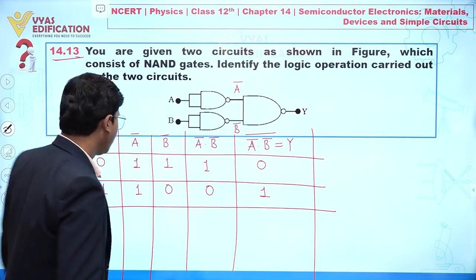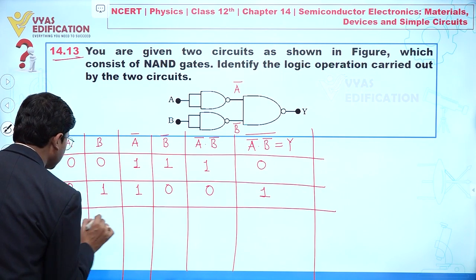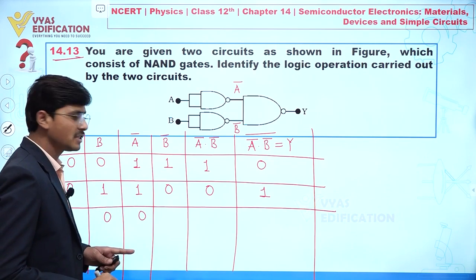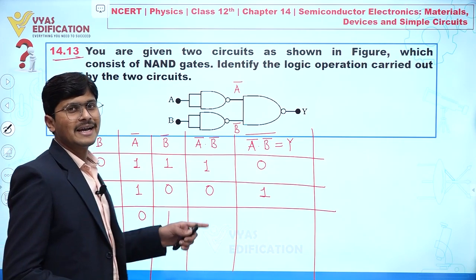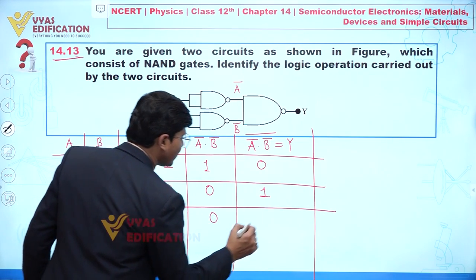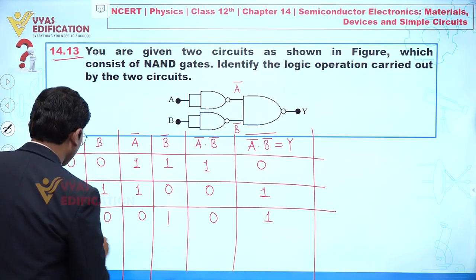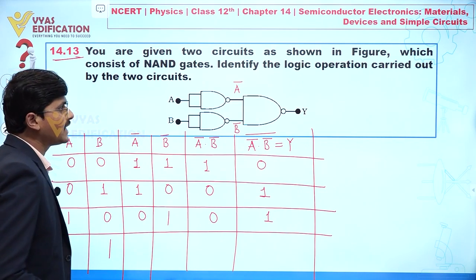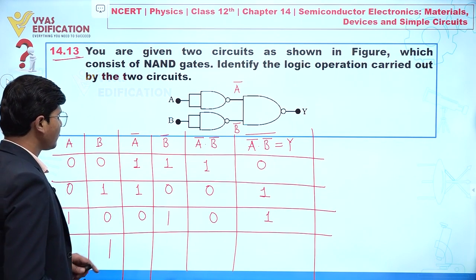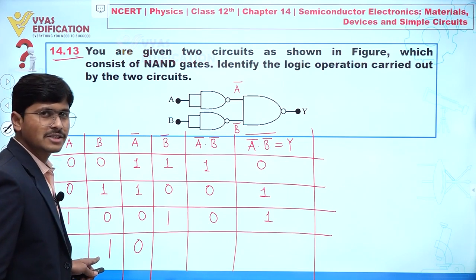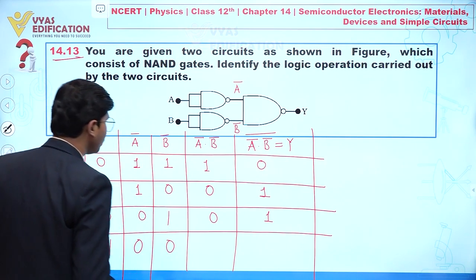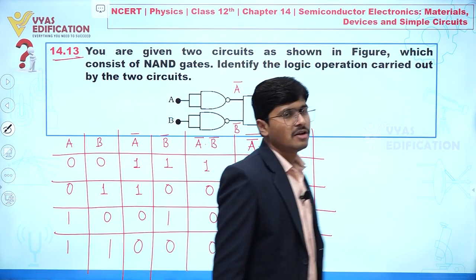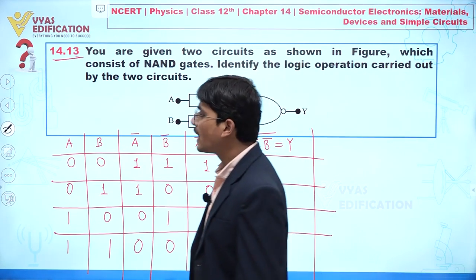Now listen carefully. Let's suppose I am taking 1 and 0. For that one, we have the input 1 and 0, we are getting 0, and now we are getting 1. Next one, last one. Let's suppose I am taking 1 and 1 as input. This is 1 and this is 1, so NOT of 1 is 0, again 0. 0 and 0, we are getting 0, and after the NOT, we get 1. Now if you concentrate on the input and output part.